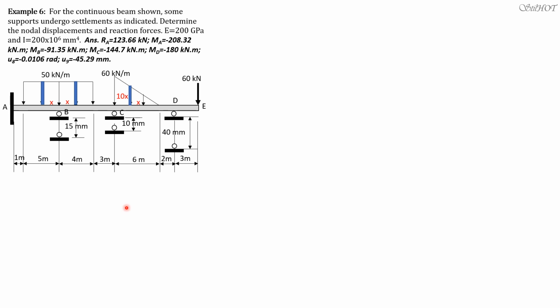So moment AB can now be set up, theta A is 0. So moment AB equals 2 times EI, 40,000 over L, times 2 times 0 plus theta B minus 3 delta over L. Because A to B is rotating clockwise, we still use minus 3 times delta. And delta is 0.015 meter, 15 mm, or 0.015 meter divided by 6. Then minus the fixed moment at A, which is negative, integral of 50 dx times 6 minus x, x squared over 6 squared. So that's the integral.